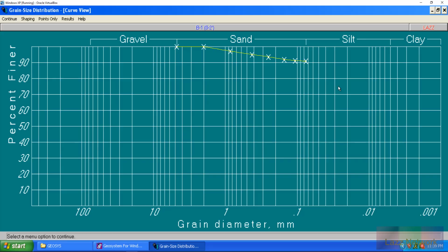Your density of water becomes greater as it gets colder, which, if you think about it, ice. As it gets colder, your density will become more, hence your specific gravity will become higher. Unlike if your water is warmer or hotter, your specific gravity will be lower because, I don't want to say the chemical change of it turning into steam, but it's also all the molecules and particles moving around.